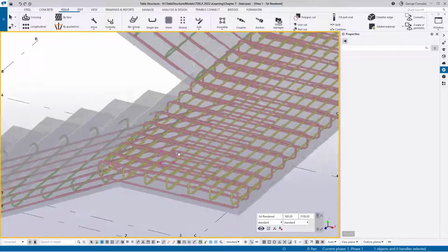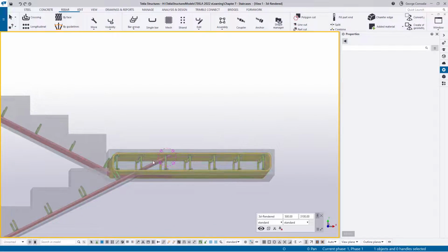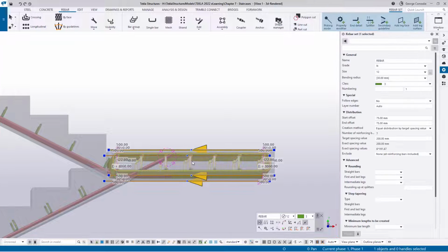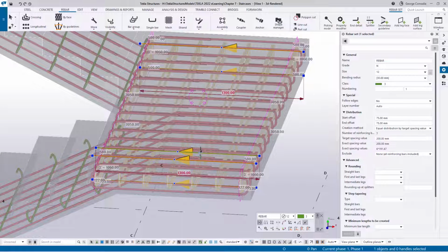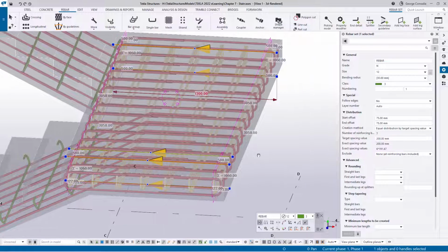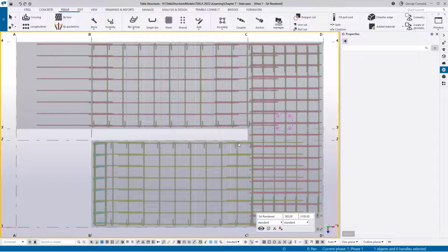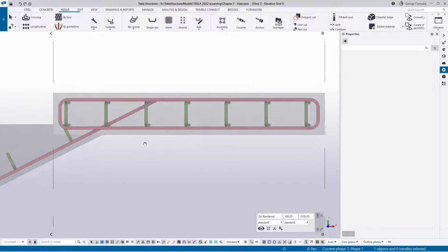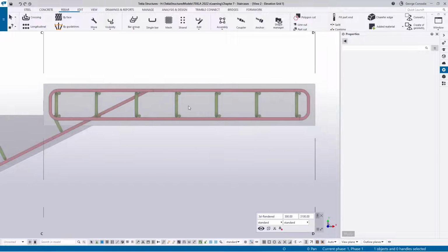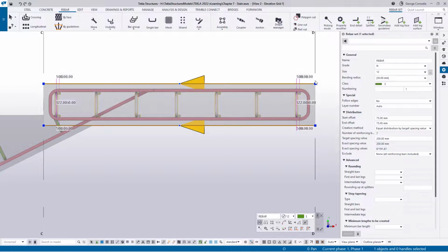The only thing we now need to look at is the clashing on this end here. So if we click on that, we look at our spacing line again. There are a lot of lines over here, but if you look at the spacing line, this is the light yellow one. So this is the start, that's the end. We can just play with spacing a little bit. So let's go to grid line 1 and have a look at it here. We want to address this clash here. We know if we click on the bar, the start is at this end. So let's try a few things. First thing is I can see it's odd spacing. Let's try odd end space, an odd last space, modify.